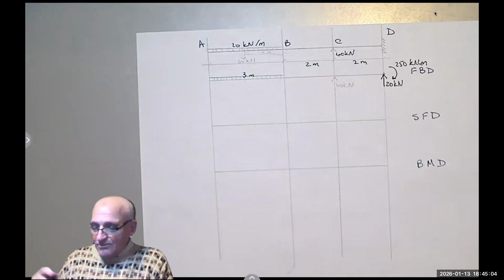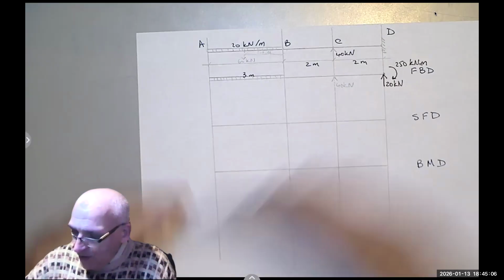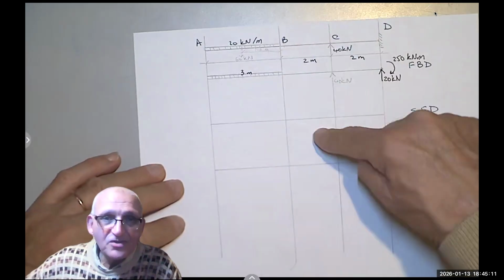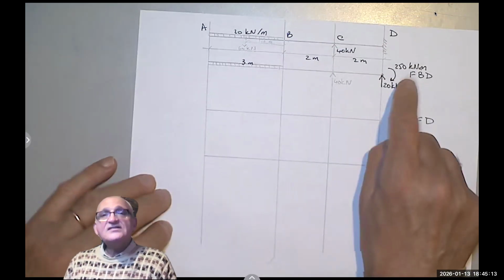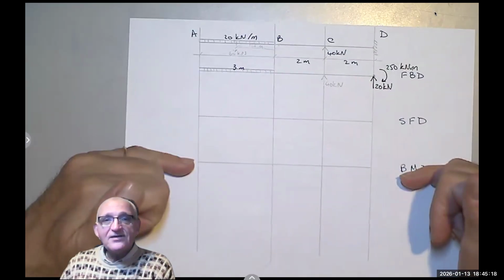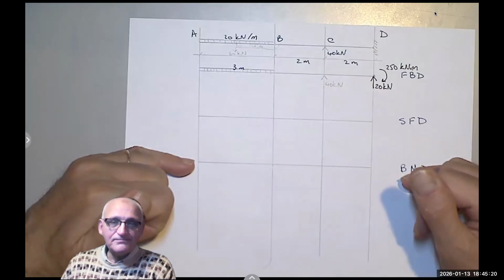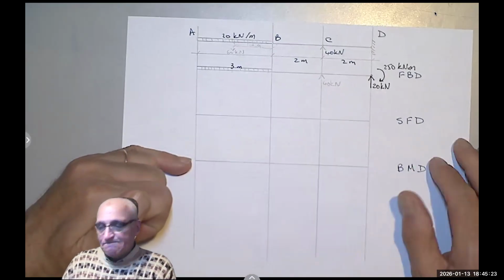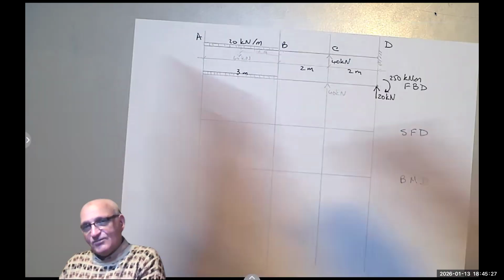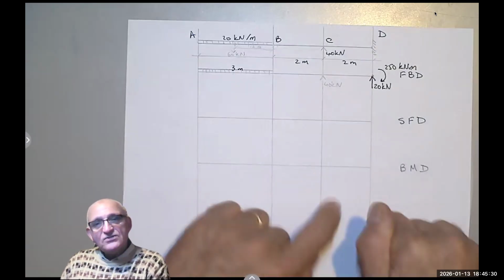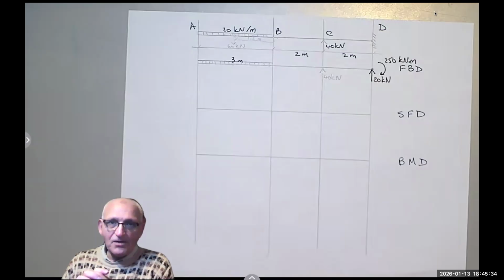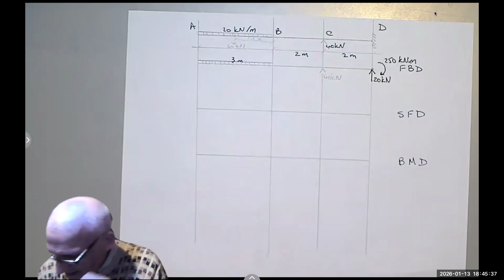When we draw the bending moment diagram, what we consider a negative moment in the reaction, going clockwise, when I draw the bending moment diagram, I will say this is positive. Maybe we'll explain that later. And if it's going counterclockwise, which is a positive moment when I calculate moments, I will consider it negative for the bending moment diagram. Okay? So be careful about that.